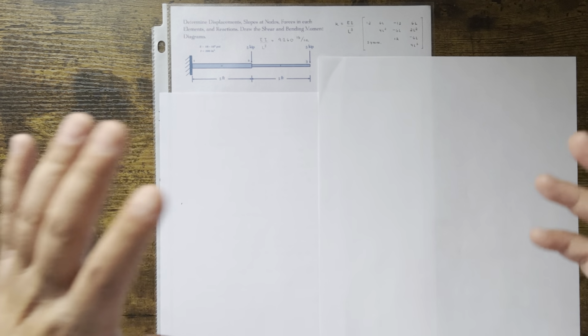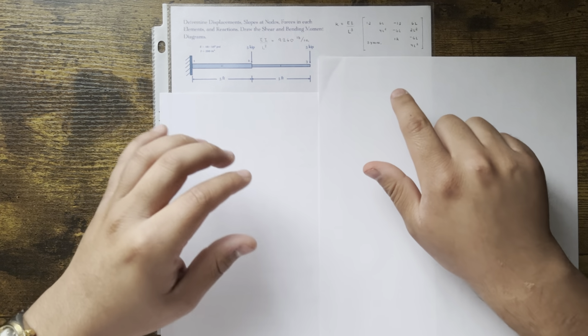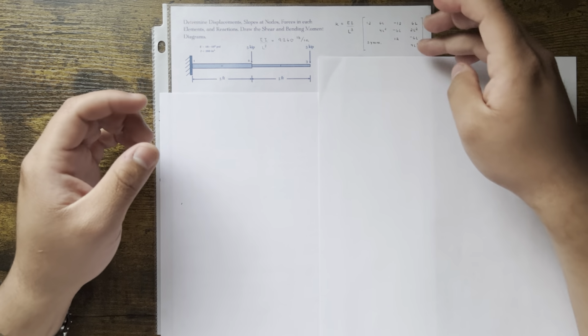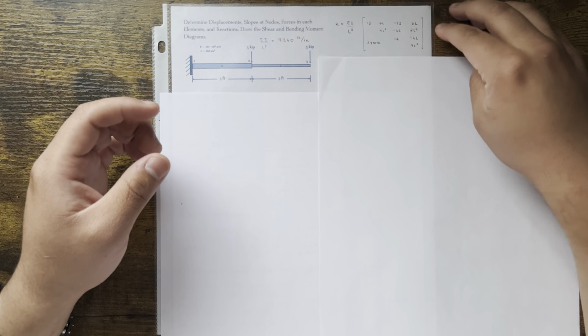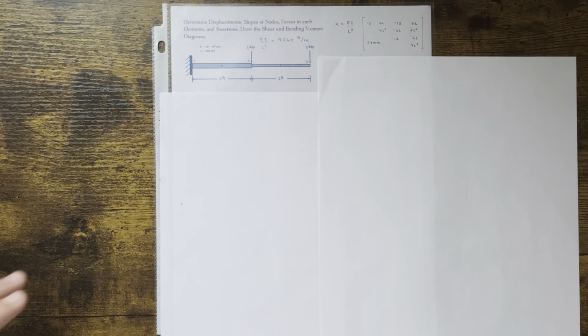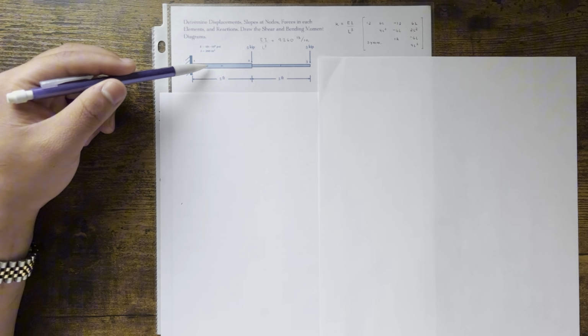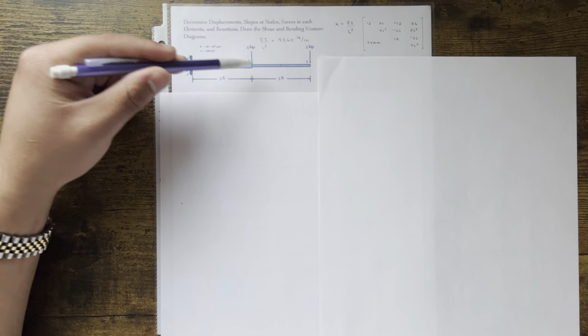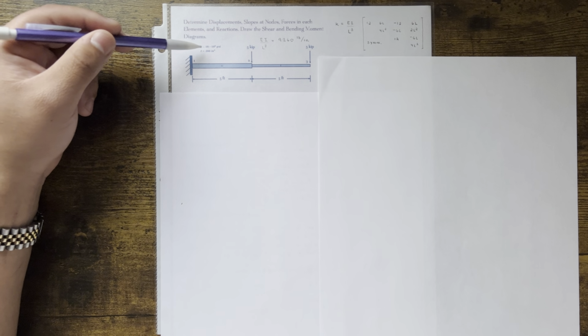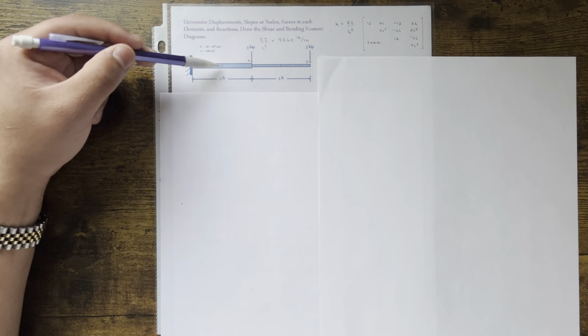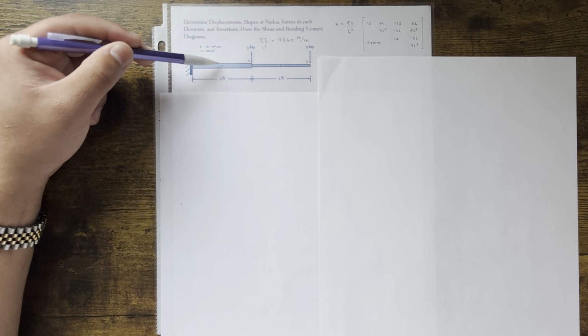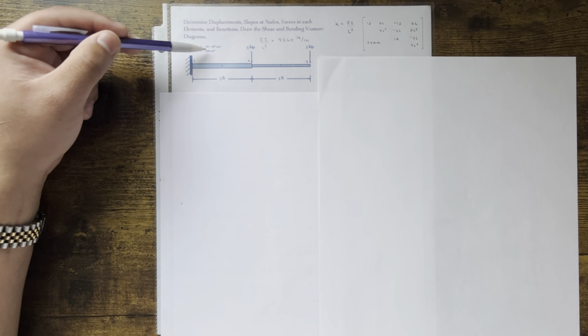All right, so nothing crazy, right? Same thing, just like the other problems. We start off with our stiffness matrix, and we're going to apply this stiffness matrix to every single element. Let me get a pencil real quick, just so I can point at things. In this case, the only difference between these two beams, right? You have two 5-footers, and they have the same material, E and I, but this one has 2 times the moment of inertia.